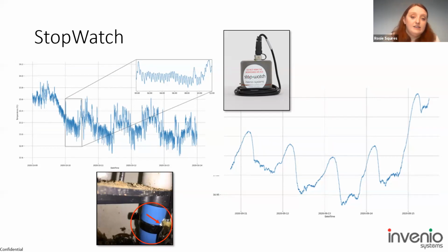We can see that in our data. We call them regular peaks, because it looks like use events at a regular period of time. This can vary from every 5 minutes to every hour, but it happens throughout the data, at night time and during the day. From that, we can indicate that it is likely a plumbing loss, and that is where you want to look.